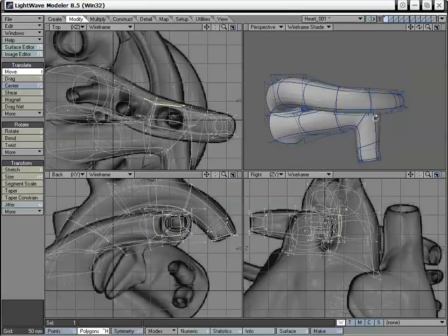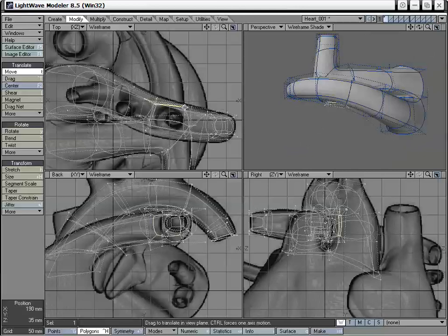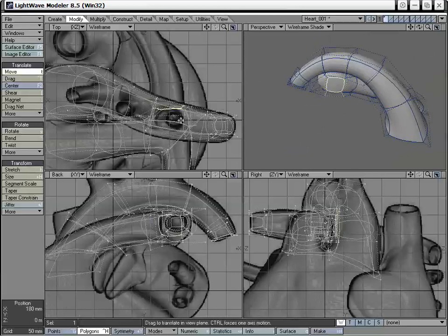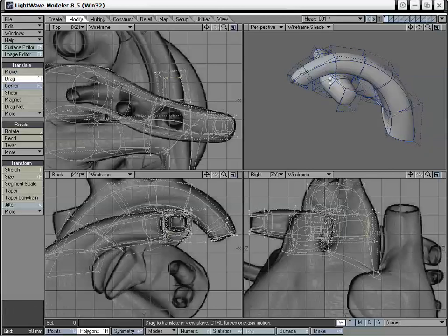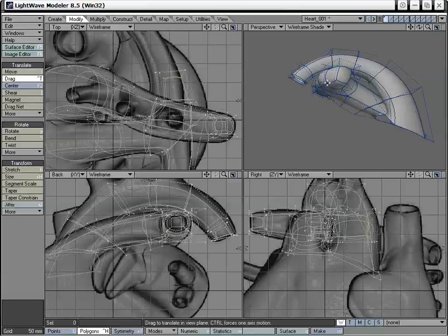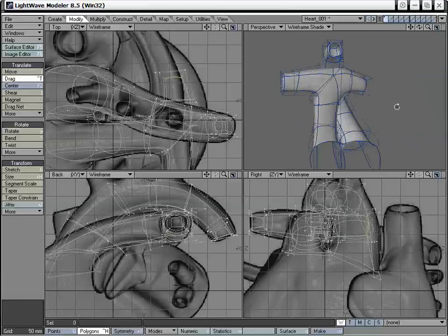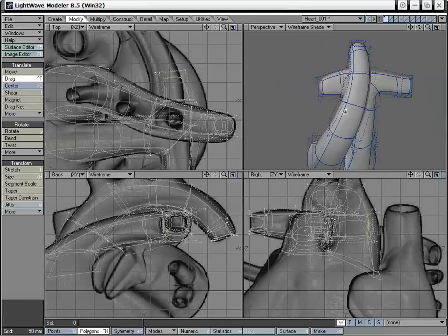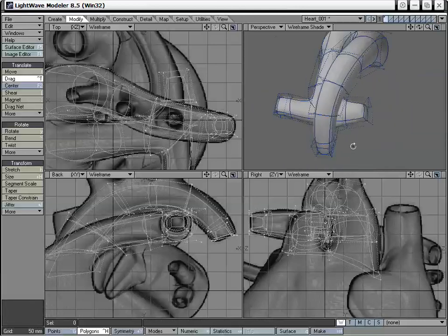And as you can see, we want it to be a nice transition, but right now we have kind of a weird looking effect, so we want to stretch that inward, rotate it back just a little, and then we're going to extrude from there. But first we want to make sure we get this kind of set up correctly. Shift F, right mouse click, and move that out. And now we can play around with this. Shift T just to make this look a little bit better and a little bit smoother. We're also going to add a little bit of geometry in here, so we can clean it up a bit, because it is kind of a crude method, but once you get enough geometry in there, it should look fine.